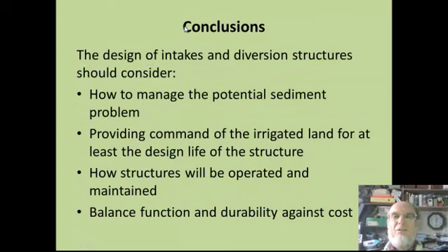So, conclusions from this talk: design of intakes and diversion structures should consider, firstly, how to manage the potential sediment problem, how to provide command of the irrigated land for at least the design life of the structure, preferably more, how the structures will be operated and maintained, and then have a design that can balance function and durability against cost. Thank you.